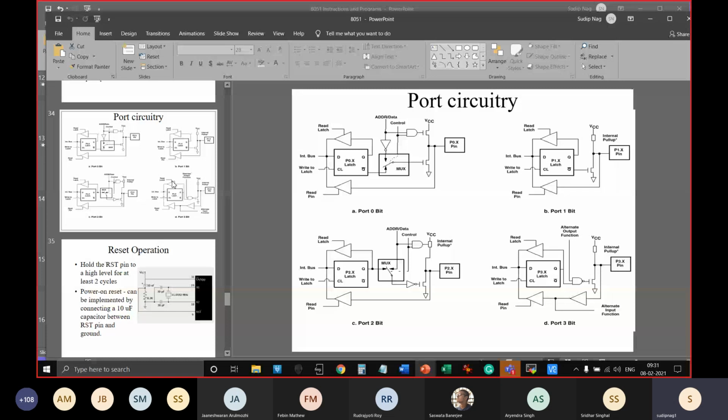Whereas for more modern microcontrollers, there is a multiplexer. This kind of multiplexer is used along with the pins at this point, where you take it to the rest of the circuitry or the alternate circuitry of the IO ports. By setting the multiplexer, which is not just a 2:1 multiplexer but may be a 1:something, some X multiplexer, it determines the input direction, output direction, and alternate functions. There could even be multiple alternate functions for every pin, more than one.